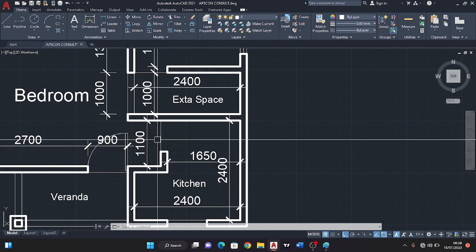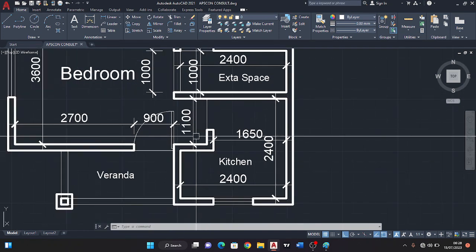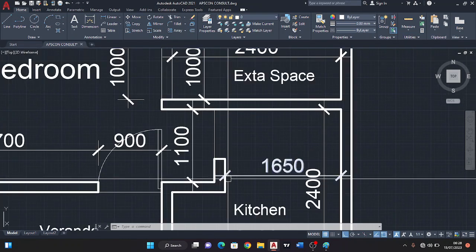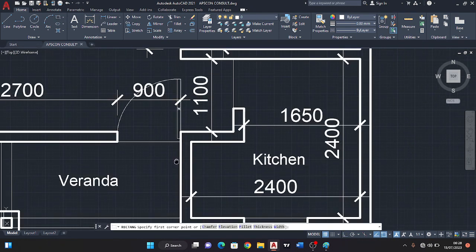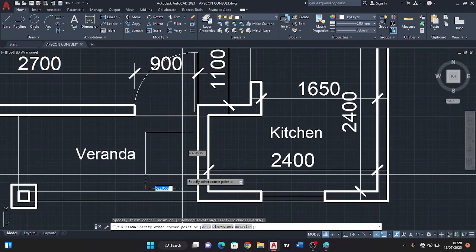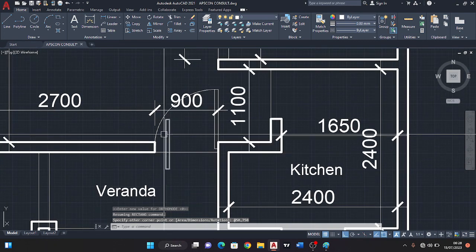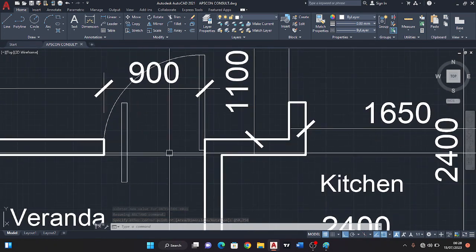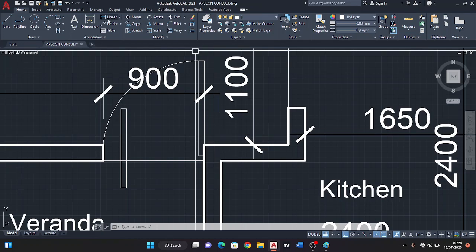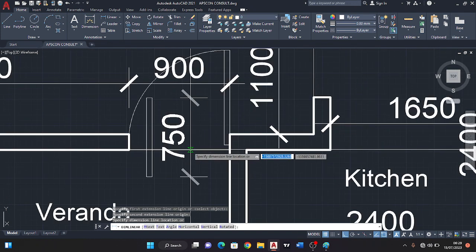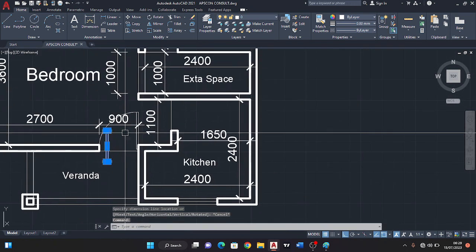Now, what about fixing the one of 750? I still do the same thing. Select this, come here, draw it, and still holding it, type shift at 50 because it's the same thickness, comma 750. Say enter. 750 is the width of the door for the kitchen and toilet. If you take your dimension, you discover that they all have the 750 value as we activated it earlier.